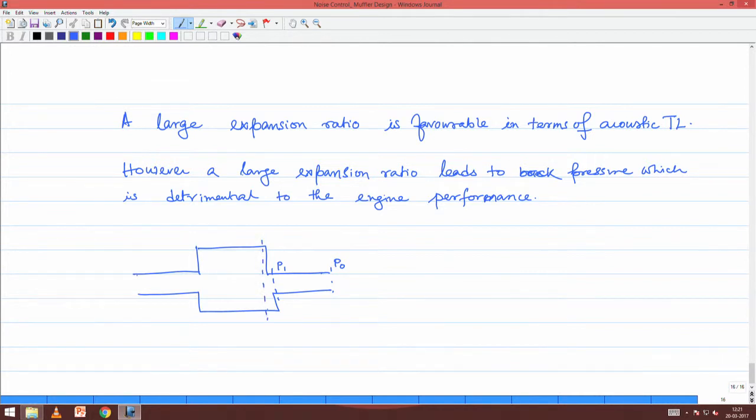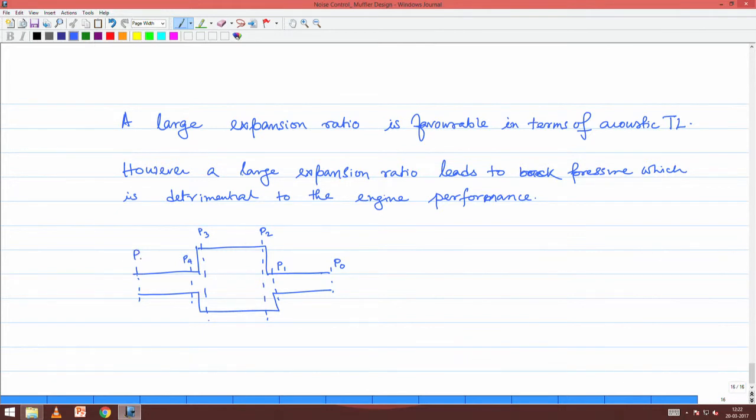Similarly, in fluid mechanics it is well known that when you have a sudden contraction or a sudden expansion, either way the flow suffers some head losses, which means at each of these progressive stations the pressure must be higher, so that the mean flow can happen. There are head losses due to pipe flow, due to sudden expansion, due to sudden contraction, which means that finally, at the engine outlet, which I can call station 5, P5 will have to be greater than P4, greater than P3, greater than P2, greater than P1, greater than P0.